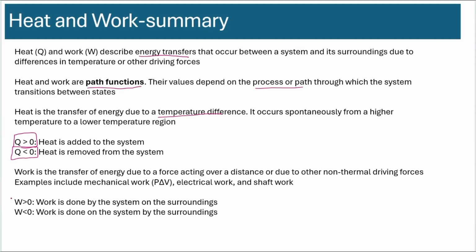Now that is quite opposite for work. If work is done on the system, it's negative. If work is done by the system on the surroundings, then that is considered positive. Work is basically the transfer of energy due to anything other than a temperature difference. So it could be due to a force acting over a distance. It could be pressure-volume work, electrical work, shaft work, spring work, etc.